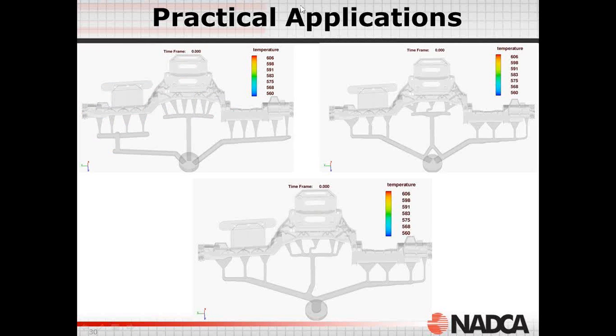And here's another very quick example. There's a brand new part, and we were looking at which gating system would be good at filling this very thin wall part. We haven't completed this study, but I'm just showing you a quick evolution of runner design and why we had to make some changes to be able to decrease the kind of cold flow defects that occur.